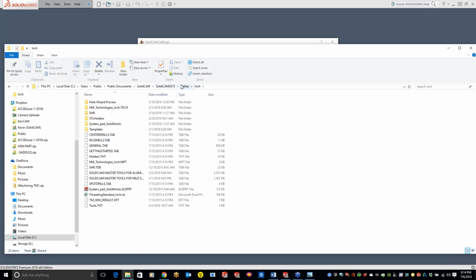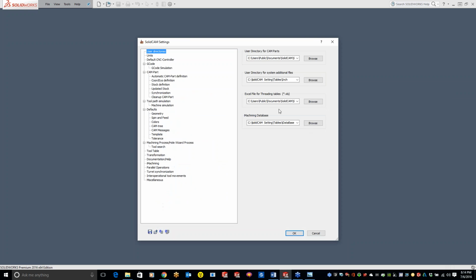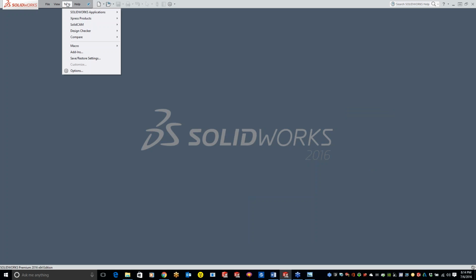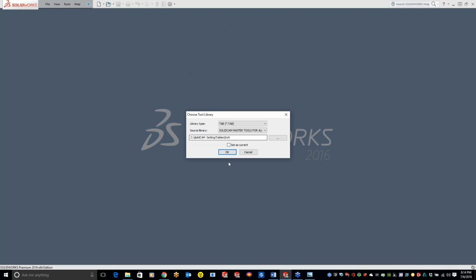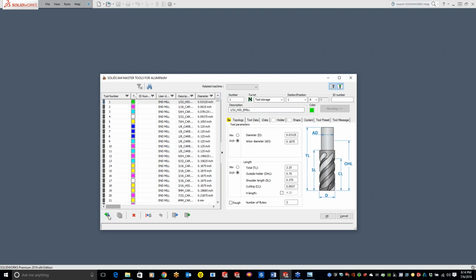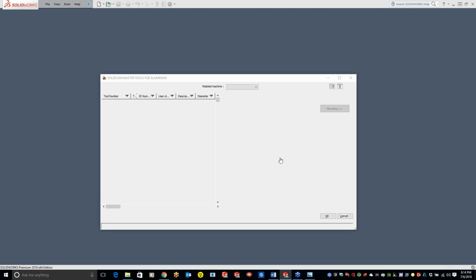So that kind of is the table's inch area. Now, the one right underneath it is the thread milling standard, and that's just when you pick a thread mill. For those of you that don't know, you go in there and you have a chart. And in that chart, you can pick your 1024, your quarter 20. Let's just open it up here and I'll show you. And we'll just go to our tool library and edit one real quick just so I can show you what I'm talking about here.